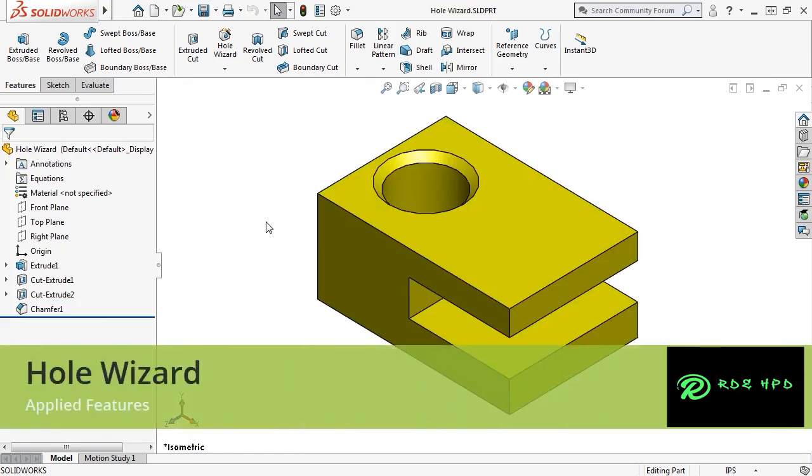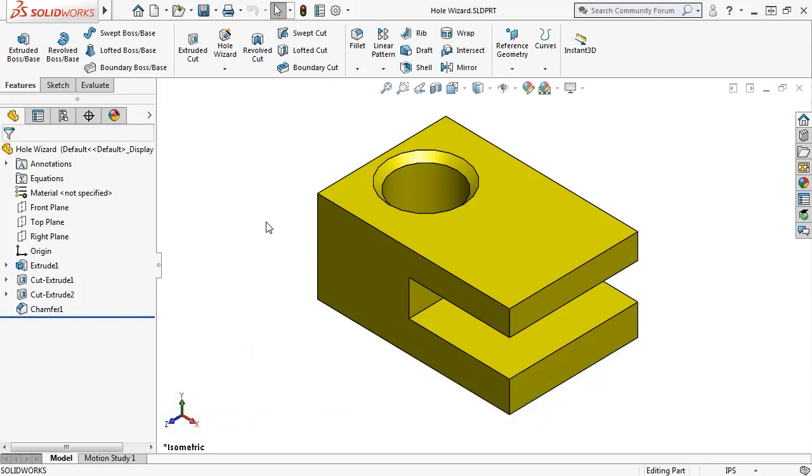One of the more repetitive tasks, typically performed in mechanical design, is the creation of holes for standard-size bolts and screws. Solidworks provides a time-saving feature called the Hole Wizard, which automates this task. For example, if you need to add a counterbore hole on this face that is properly sized for a 1/4-inch panhead screw, you'll just click on this icon to launch the Hole Wizard.